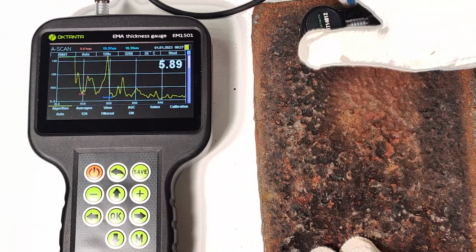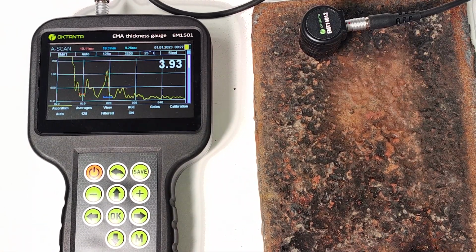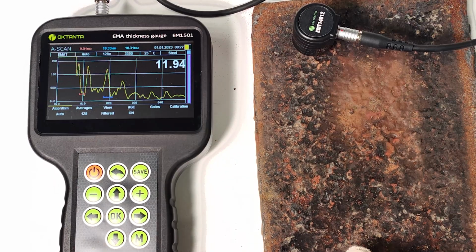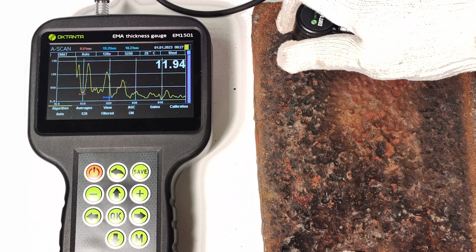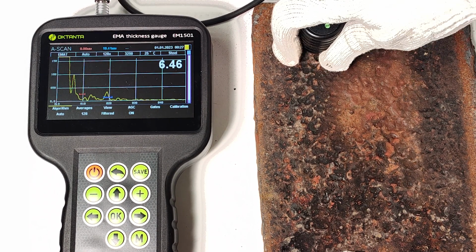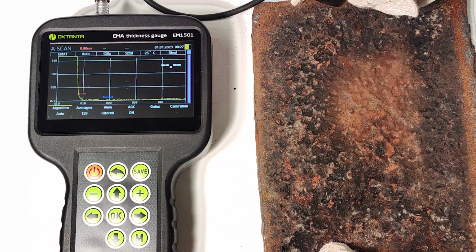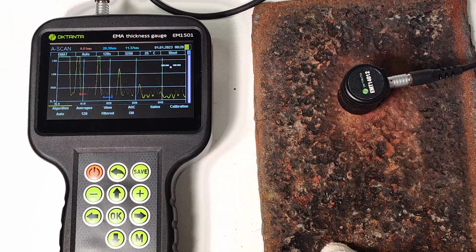But in the presence of severe corrosion, this process changes. For a given 8 mm thick object, we can find areas where the regular A-scan shape turns into an almost random signal. Corrosion of the opposite surface of the object leads to reflection of waves in random directions. We can conclude that there's a defect in the test object, which unfortunately prevents us from taking measurements.